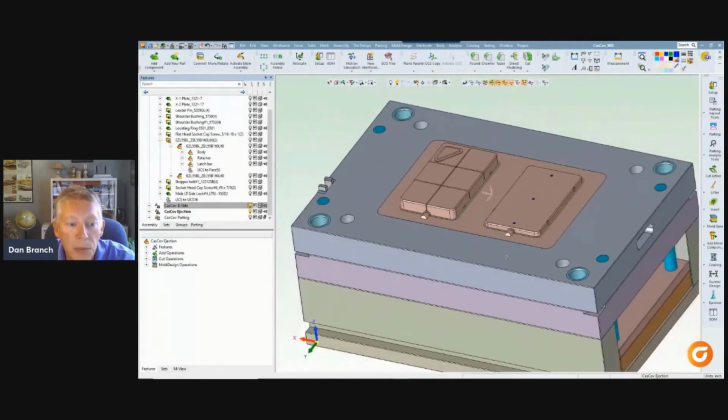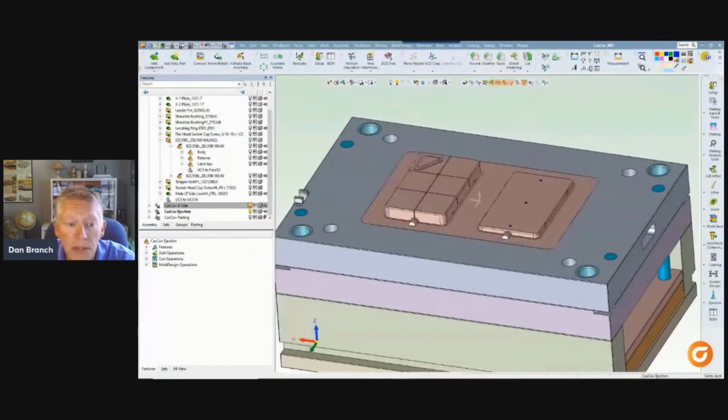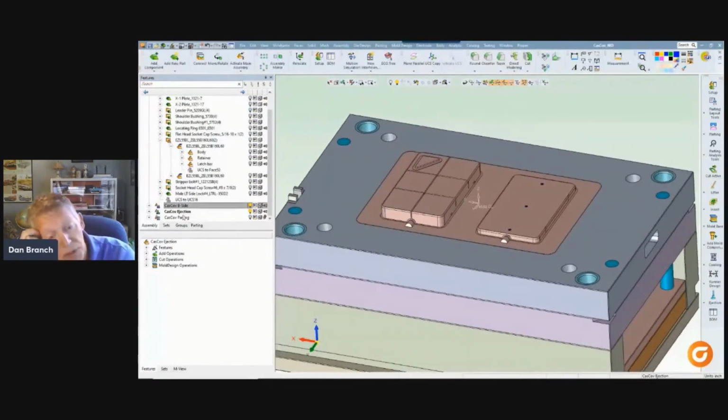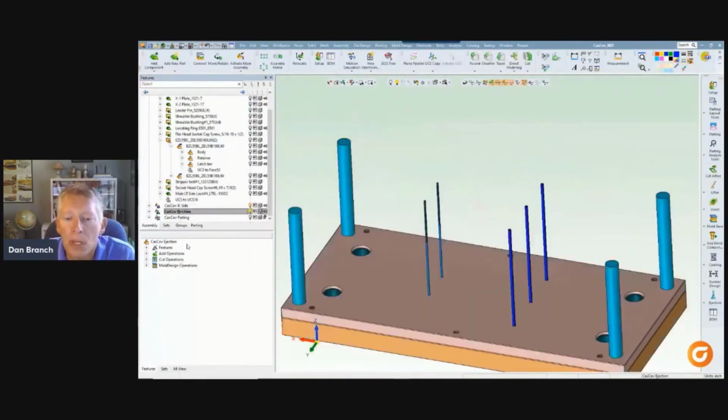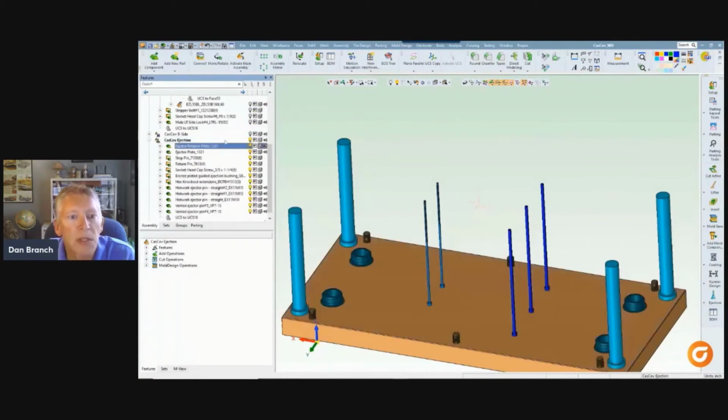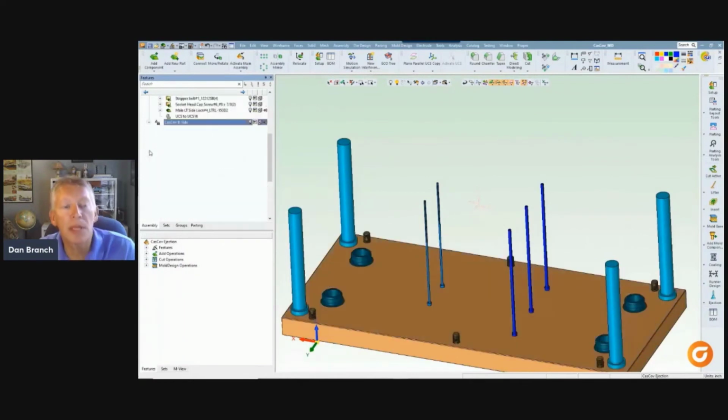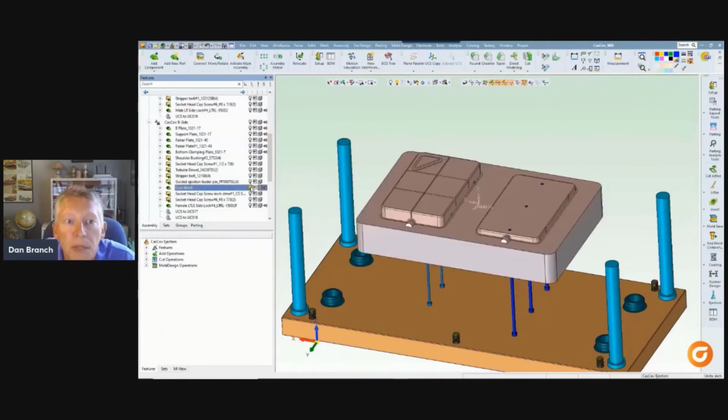Okay, well, now it's really time to look at placing some lifters that will mold and release the undercut features in these parts. Let me turn off a few plates so we can see a little better. And then I'll be heading back into the DME catalog again, this time for one of the new style AccuAlign lifters.